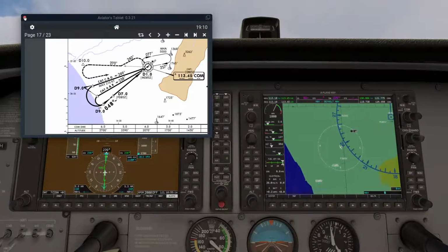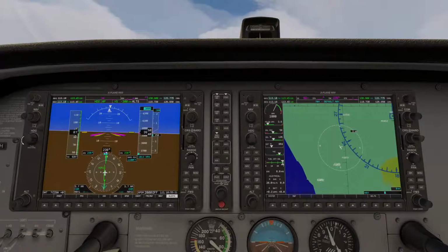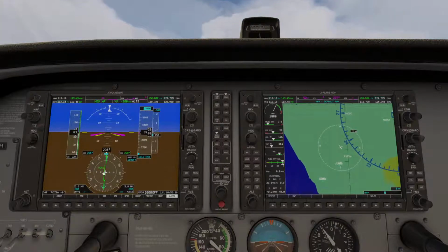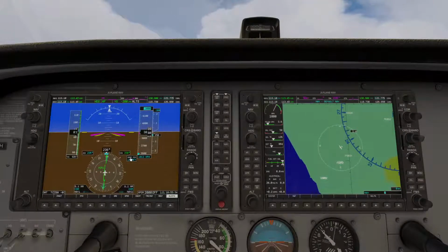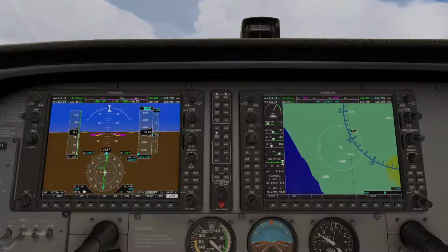One to go. Let me set the heading to 236 to correct the CDI deflection, which is almost to the left, and bring the CDI center, and continue on course 238. 6 mile out of VOR and descending to 3000 feet.